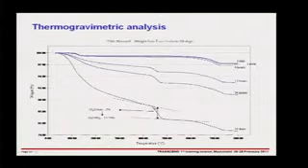So a lot of studies have been made. What's the most accurate measurement method for dealing with this weight loss from calcium silicate hydrate going on in the background? And the best method we can find that compares well with other techniques is this tangent method. By this we mean that you construct a tangent here which continues this slope, and a tangent here which continues this slope.